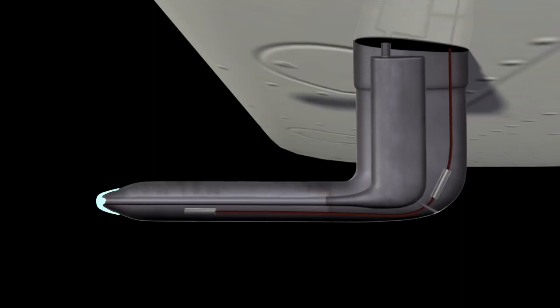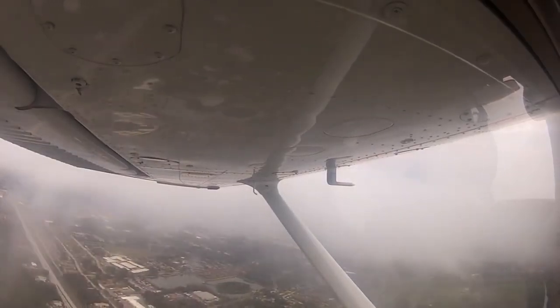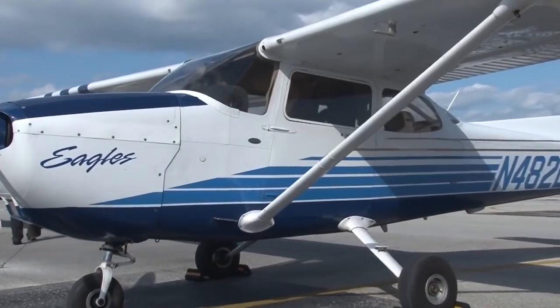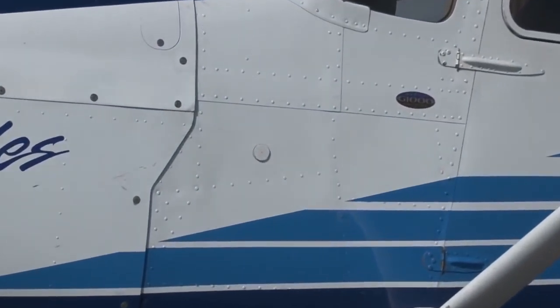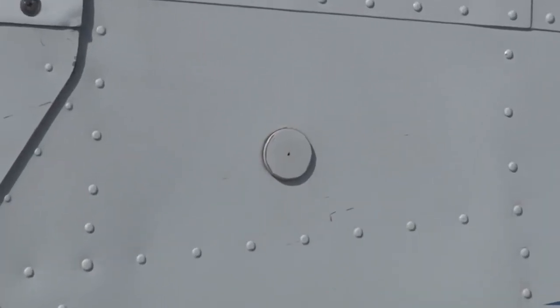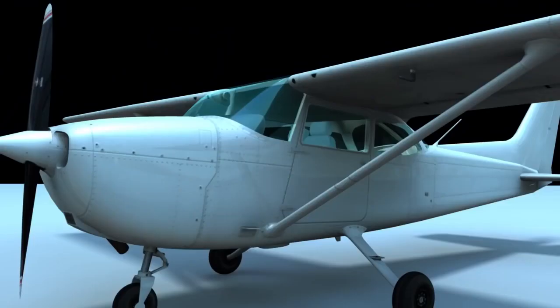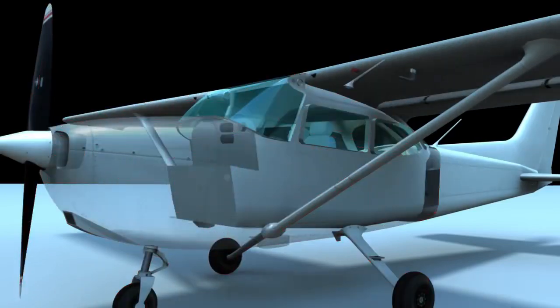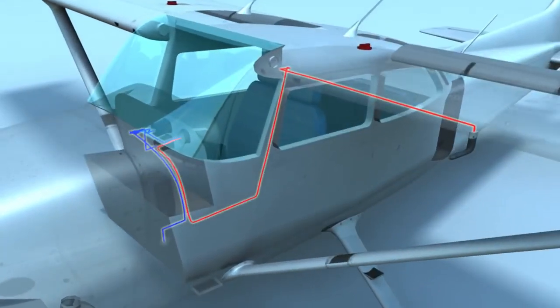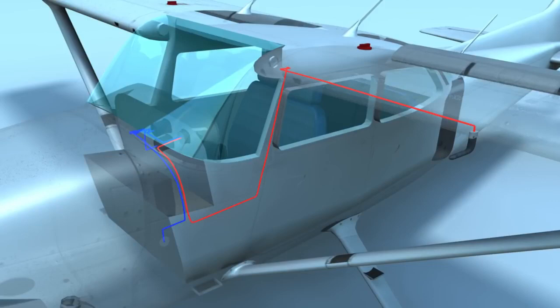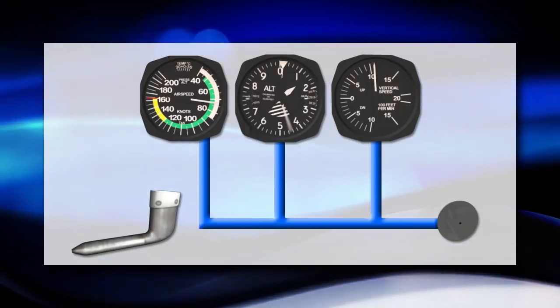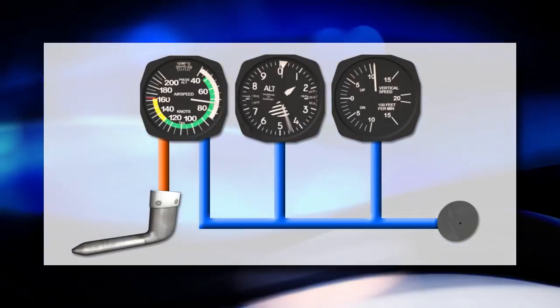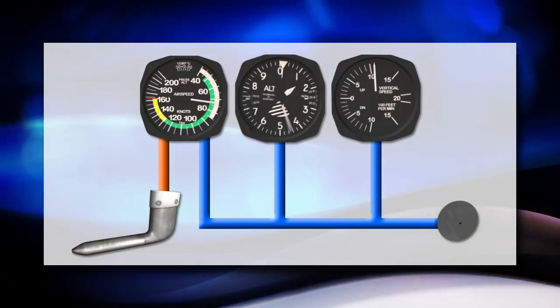The counterpart of the pitot tube is the static port. The location of this port will vary with different aircraft designs, but should be in a location where it can measure the static pressure of the air, unaffected by the dynamic airflow around the airplane. On the Cessna 172, the static port is located on the left side of the forward fuselage. The pitot tube and static port openings are connected to tubes that join into the pitot-static instruments. The pressure inside the instruments match the pressure of the outside atmosphere. All three pitot-static instruments connect to the static port, but only the airspeed indicator connects to the pitot tube. Sounds simple, right? Let's discuss how each pitot-static instrument works.